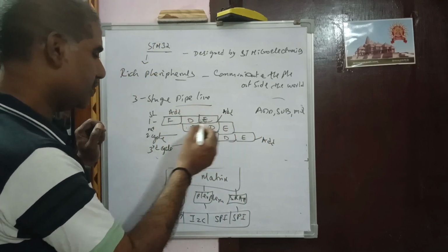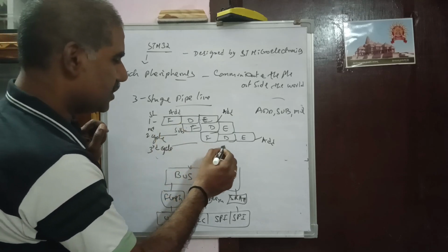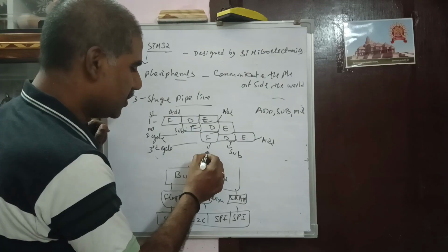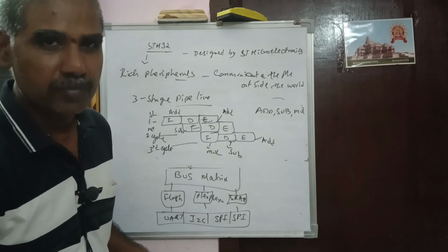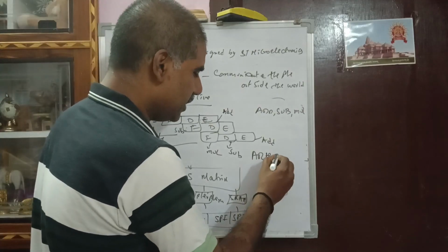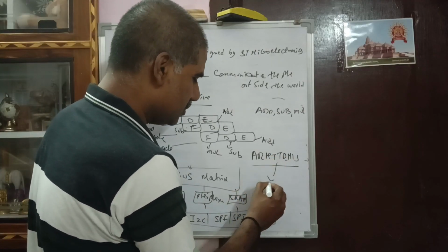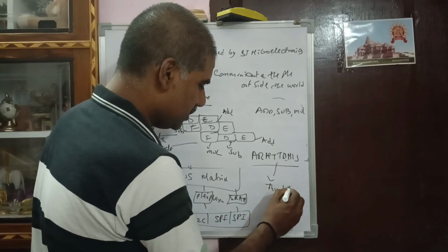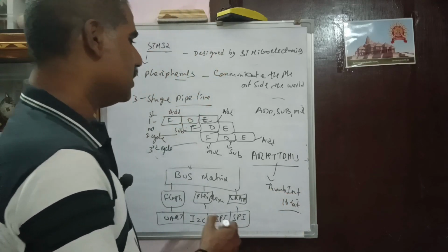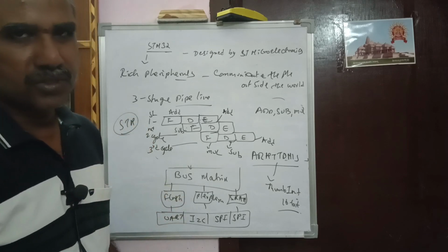Whereas in the second cycle the subtraction is fetched, then decoded, and the multiplication is fetched. Like that, the pipelining process is supported. Whereas in ARM7TDMI also, it follows the Thumb instruction set, which is 16-bit. Okay, like that, STM also supports the pipelining process.